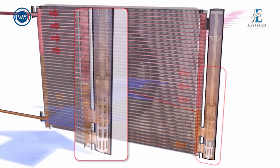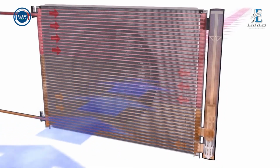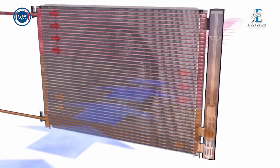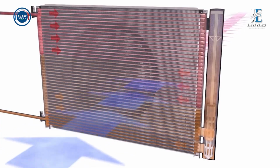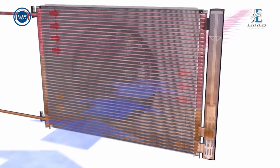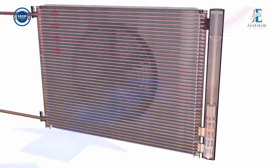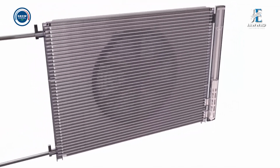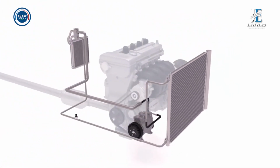The liquid refrigerant then passes to the gas-liquid separator section, where any remaining gas is separated, providing further opportunity for the gas to release heat and change to a liquid. The liquid refrigerant then receives additional cooling in the subcooling section, where the heat energy contained in the liquid refrigerant is again released through the condenser fins to the air. This further reduces the temperature and improves the overall cooling performance.